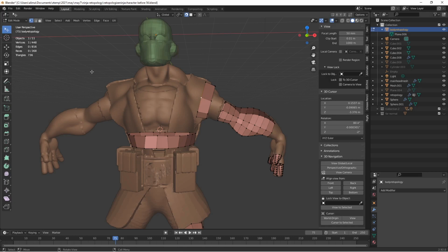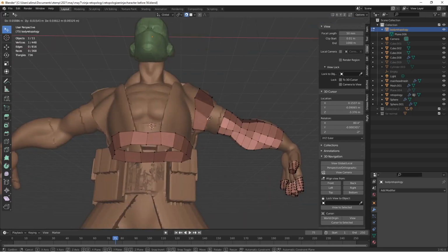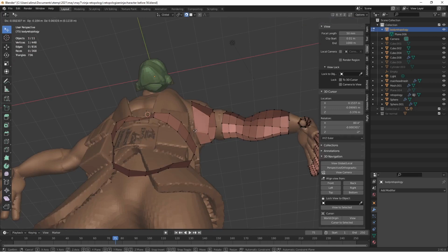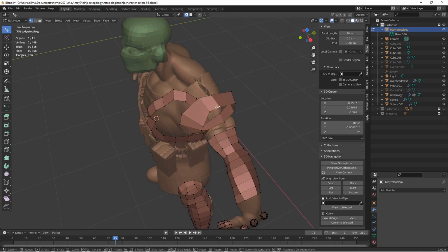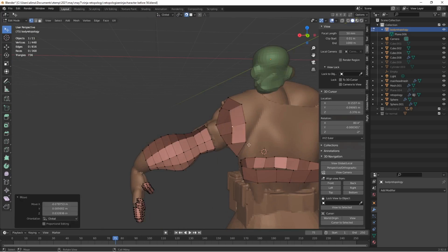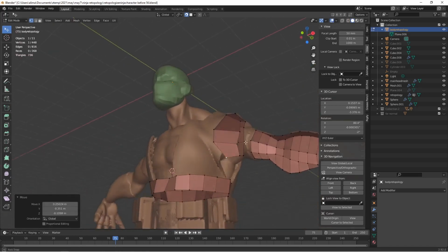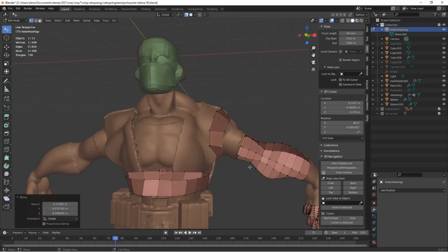This tweak mode, this tweak here, what this does is this allows you to grab geometry like vertices and then move them without being so much concerned about which axis you're on. So I'm pressing G. Oh, you know what? Yeah, with the tweak, we don't have to press G. We can grab and this will snap. So what you want to do is kind of aim the view to where you want your snapping to go. Now, vertices will not snap until you move them. I'll left click to deselect.